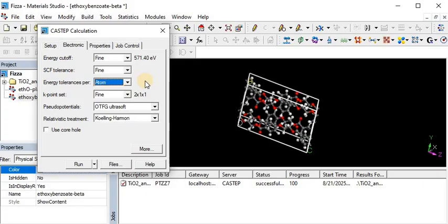Through this you ensure the optimization stops only when the energy is physically converged. We have two options, atom and cell. Per atom is used when comparing energies of differently sized systems, for example when you dope some element in your pure crystal, you should use this parameter for atom.